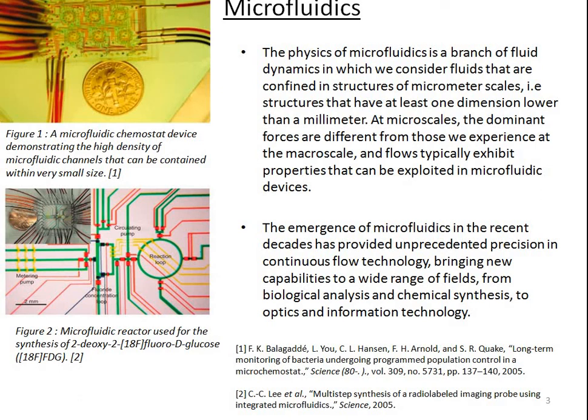The emergence of microfluidics in recent decades has provided unprecedented precision in continuous flow technology, bringing new capabilities to a wide range of fields, from biological analysis and chemical synthesis to optics and information technology. In microfluidics, surface forces are more important than inertia forces. As the surface to volume ratio increases, for the same reactant inlet we get more product output. To scale up, we can also arrange them in parallel, but that will come later on.